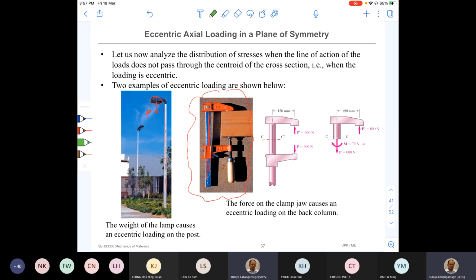And see what are the forces applied. Right. So first we see our externally applied force, 600 Newton, and then on the cross section there should be internal resistive forces. The first internal resistive force is to counter this axial force. So there should be an opposite direction force P, and it should be equal to the externally applied load.